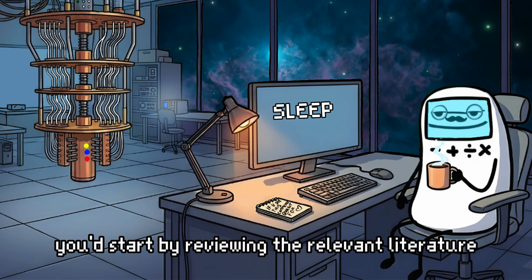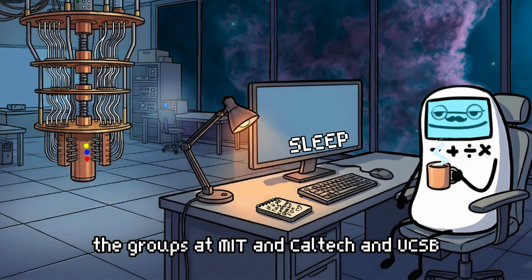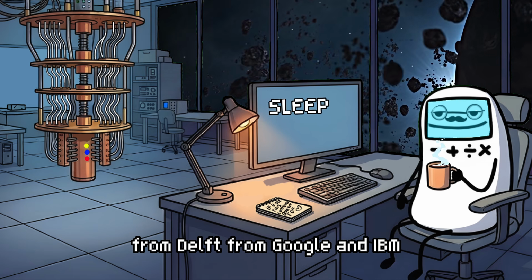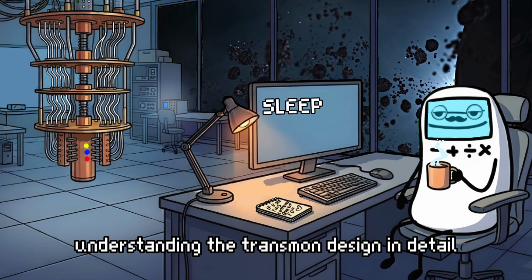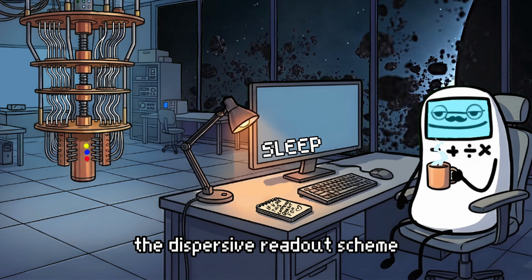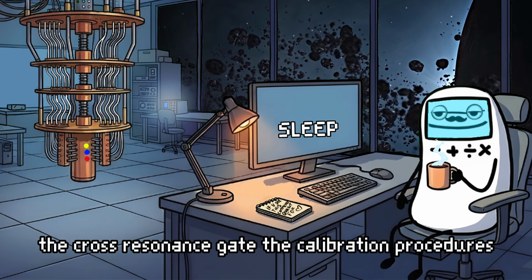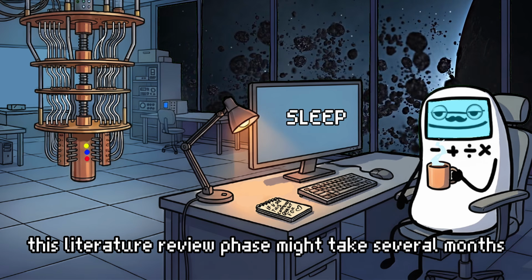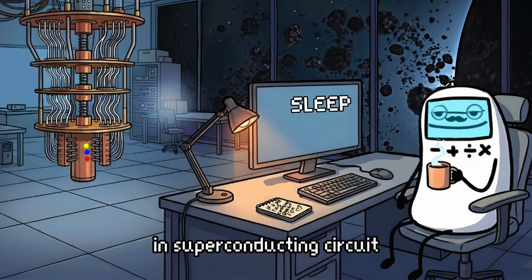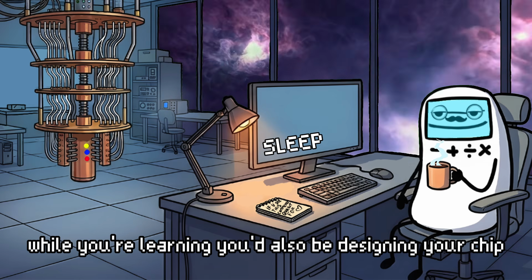You'd start by reviewing the relevant literature, reading papers from the Yale group, the groups at MIT and Caltech and UCSB, from Delft, from Google and IBM, understanding the transmon design in detail, the dispersive readout scheme, the cross-resonance gate, the calibration procedures. This literature review phase might take several months if you're coming in without prior background in superconducting circuit QED. While you're learning, you'd also be designing your chip.